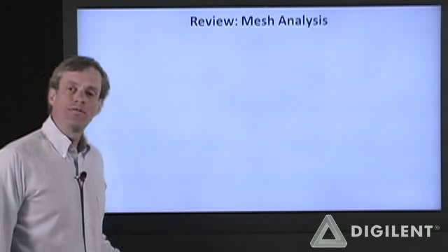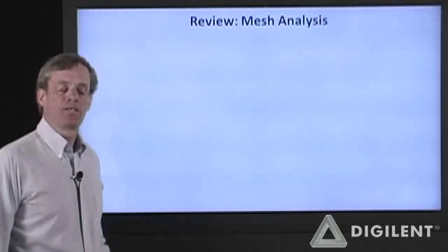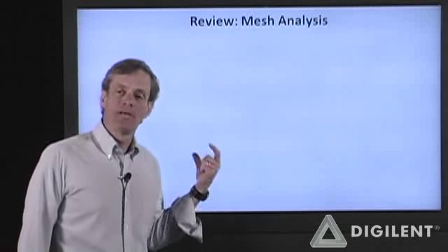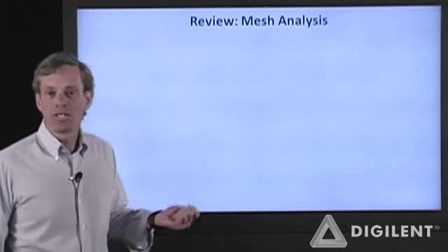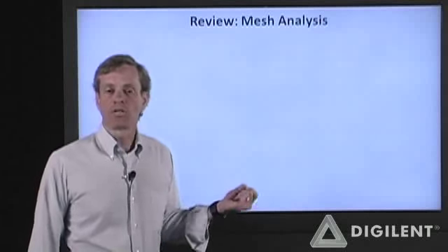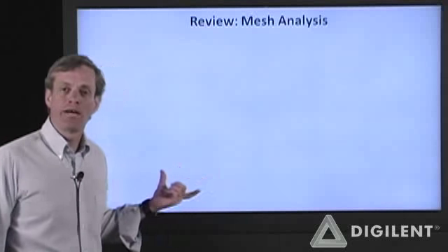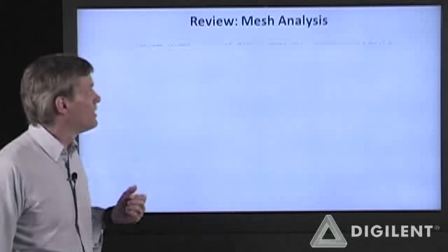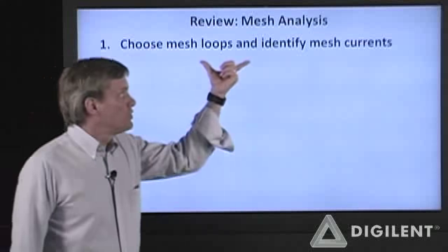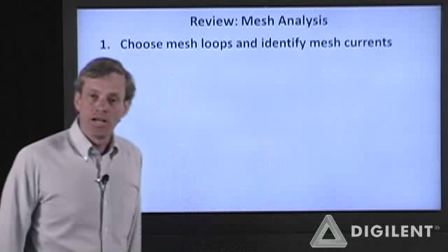Okay, a review of the steps associated with mesh analysis. And remember that I've digested these a little bit and condensed them from the approach that I gave you for nodal analysis. Each step in nodal analysis has a corresponding step in mesh analysis. What I've done is combine different steps, so I came up with fewer total steps. First step, choose the mesh loops and identify your mesh currents.